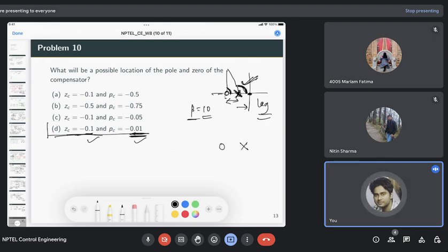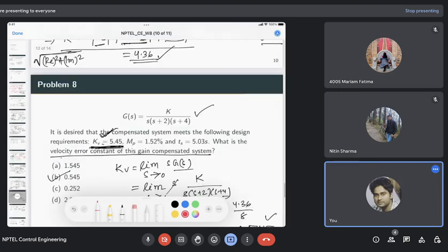Right? These are the open loop poles and zero. So as the gain value is increased, you see that your root locus will be moving like this. Okay, so this pole will be very close to this zero, the closed loop poles. So they will in effect cancel each other, and this angle contribution will be very small, because you don't want to disturb this transient specification, right?